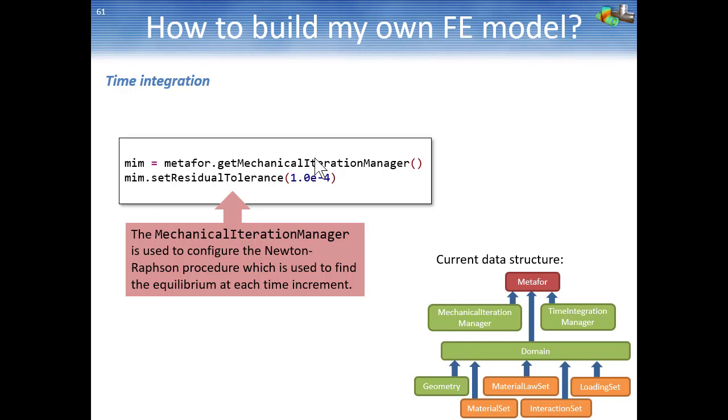So, as for the penalty coefficient, you must find the best value, which is a compromise between the accuracy, where the best value is 0 but it doesn't work, and CPU time, where the best value is a very large number.